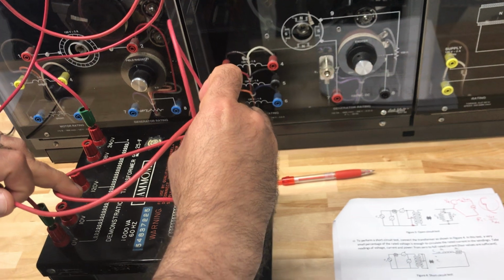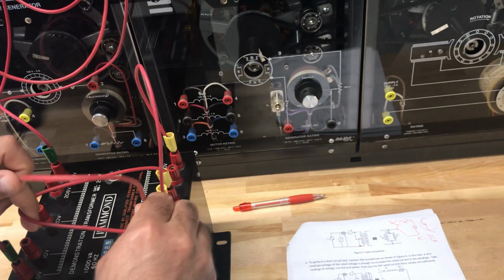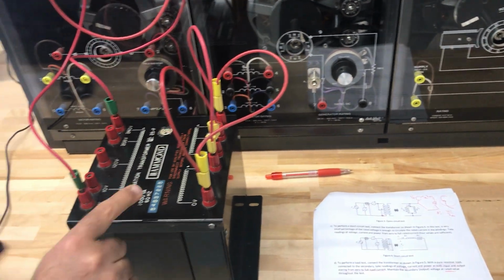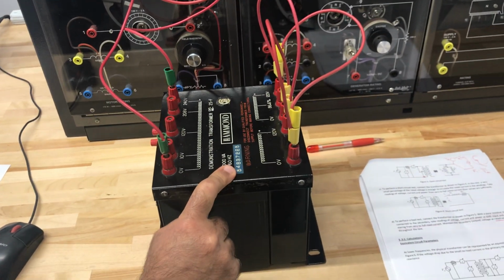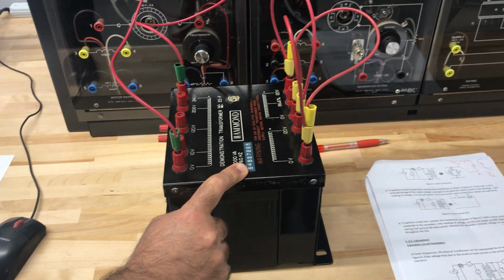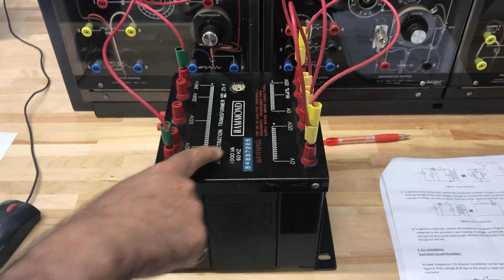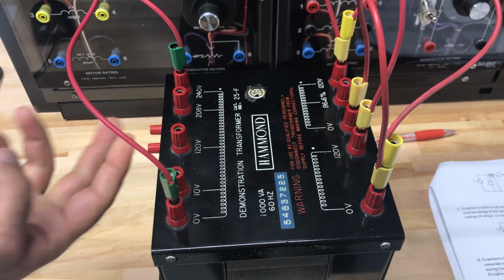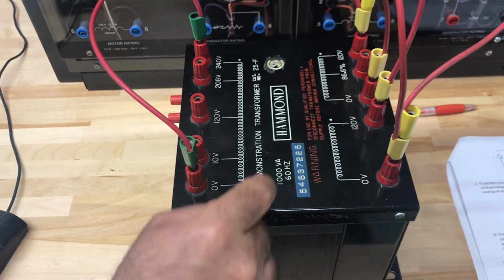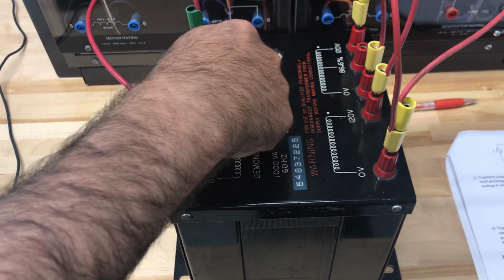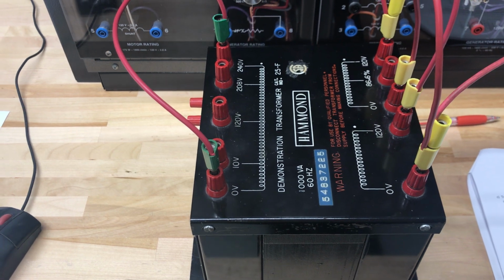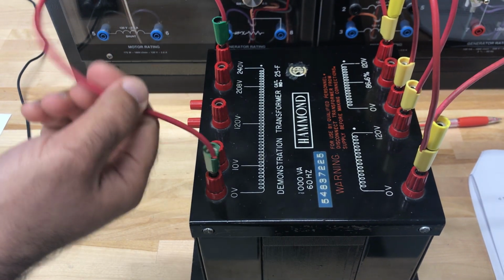I can put the short circuit between this point and this point, or between this point and this point. It doesn't matter. But pay attention again, because I don't like the current to be increased in the case of the short circuit, because the power is equal to 1000, which is S in volt-amperes. And I'm expecting voltage here maximum, which is 240. So if you divide 1000 by 240, it will give you around 4 point something for the rated or the full load current. So I'll pay attention.